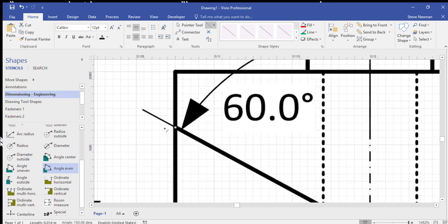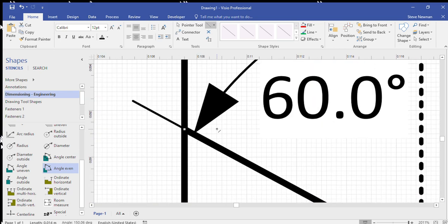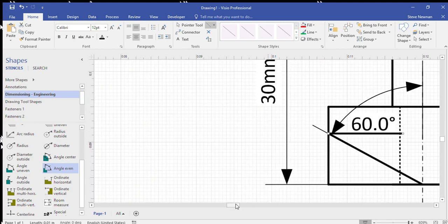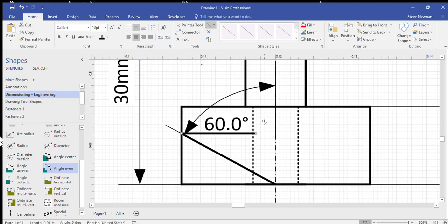Alright, now when I zoom in right over here, with my control scroll button, I know that that finished just there. I'm going to draw a line across. This is just going to be a construction line, guys. Let's zoom out again. Shift and scroll. I want to increase that all the way across. Back to pointer tool. Back across.